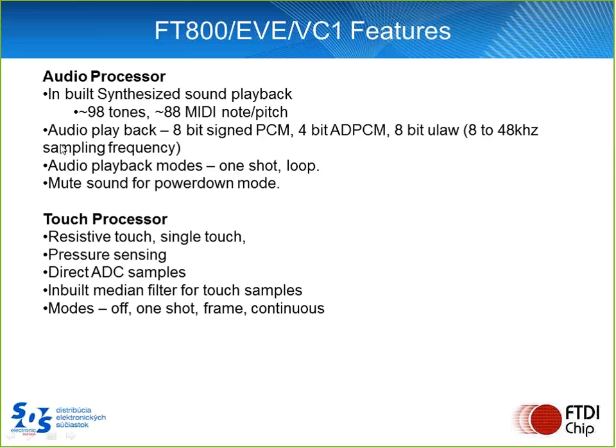The touch processor is a resistive touch, and it's a single touch. It also does pressure sensing, and it's a direct analog to digital converter. It has an inbuilt mid-range filter for touch samples, and the modes for touch are off, one shot, frame, continuous.